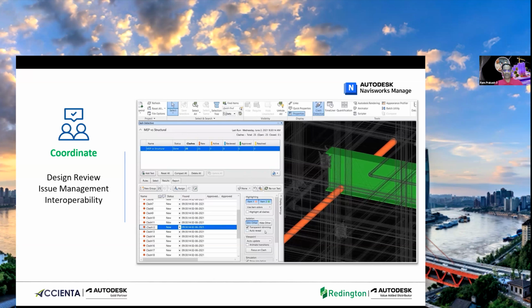So the Navisworks Manage gives you a real design review of understanding your systems, your architectural and structural elements, and the clashes. And you can also decide whether you want to mark something as a proper clash or as an issue. Suppose I wanted to find out about the carpet. The carpet is not clashing anywhere in my living room, but I have to change the color of the carpet, or the material of the carpet, or totally some other texture. I can mark it as an issue like that. And if you have a huge duct in the critical ceiling area, you can make a decision on it.